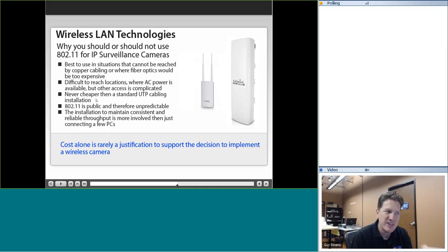In addition, keep in mind that even if you find a private pole that has the proper power source and is not turned off by a timer, your other challenge is that you now have to put a bridge product up there, a camera product up there, and potentially a light source. If you put all those things up there, you have to be very careful, because now the pole is dealing with the weight, and you may bend the pole or cause other issues with the accessories on that pole. So be very careful when customers recommend poles. It's not always the best case. However, as long as you have a power source, you can find some very interesting and attractive places to put cameras that you could otherwise not reach.